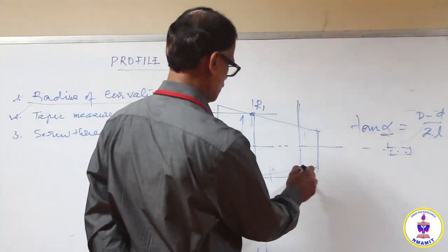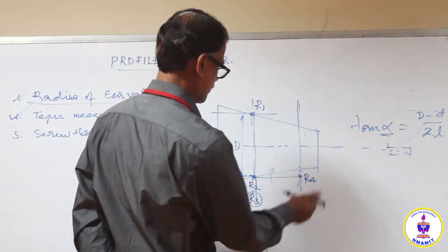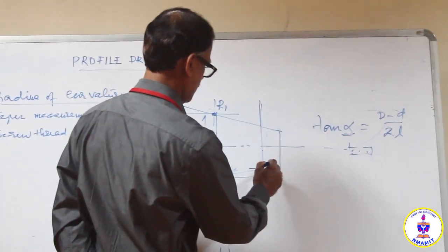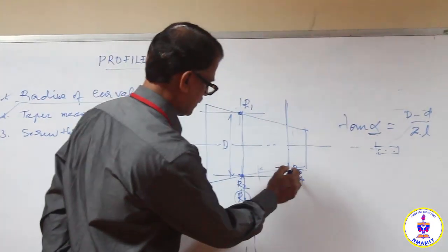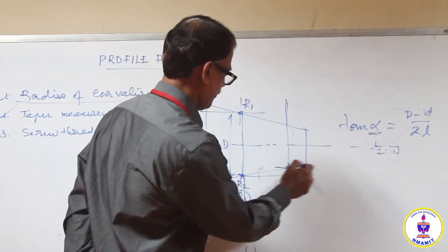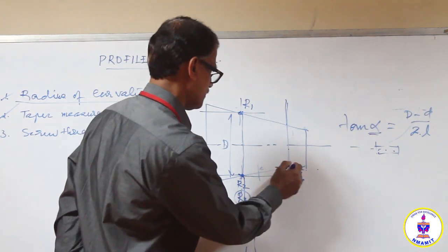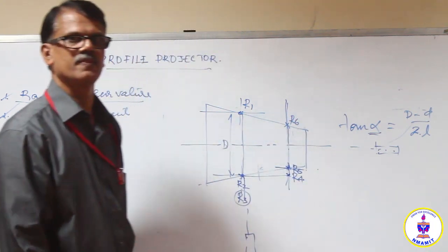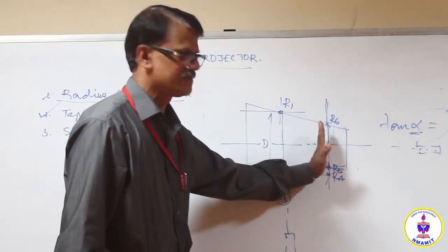Now again move the crosswire micrometer, or the first micrometer here, to position the crosswire at this position. So this is R5. So at this position, record the fifth reading as R5 and move the crosswise micrometer so that the crosswire is moved to the other side again, and this is R6. So difference between R5 and R6 will give the diameter at this section.